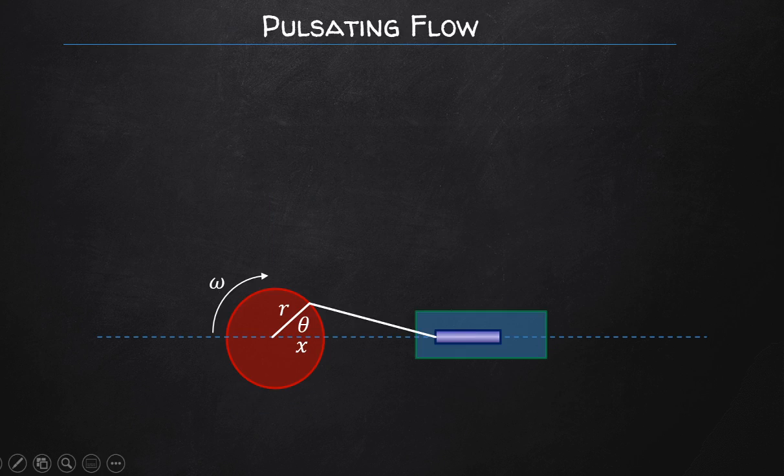Okay, so this causes pulsation. Okay, so this pulse needs to be accounted for when you're designing piping systems, if you're designing with these sorts of pumps in mind, so that abnormal or unsafe operation conditions can be prevented.